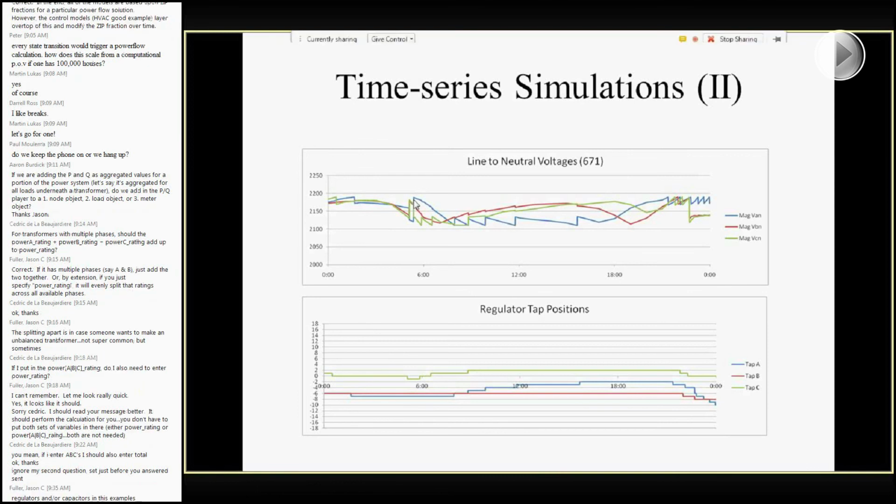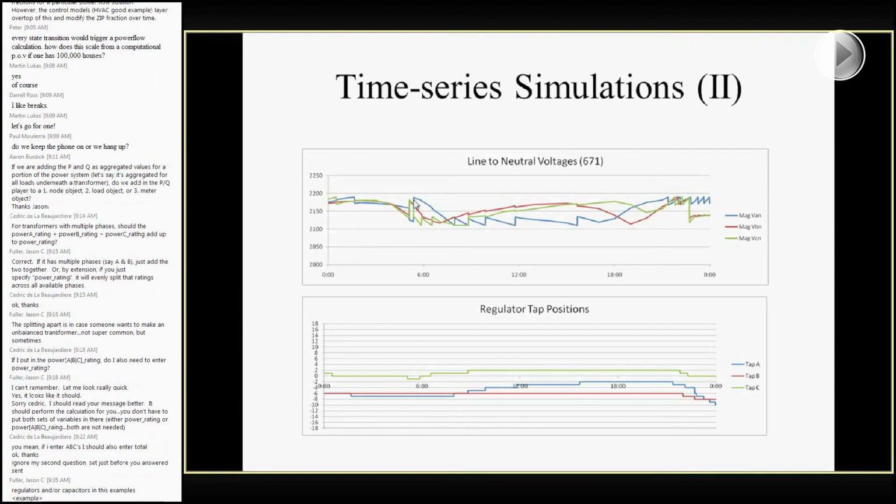I mean, the IEEE 13 node is obviously a fairly simple example, but you could see how if you wanted to do a planning level study, if you had representation of your load throughout the day, maybe your voltage wouldn't jump up like this. It would continue to go down and then rise back up later in the afternoon. You could add a regulator into your system using GridLAB-D and see what kind of benefit it might provide you, and take that back to the utility commission or whoever your governing board is and figure out if they can fund to add in an extra regulator or anything like that.